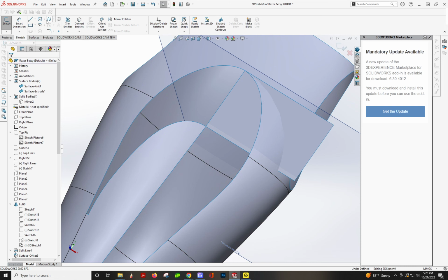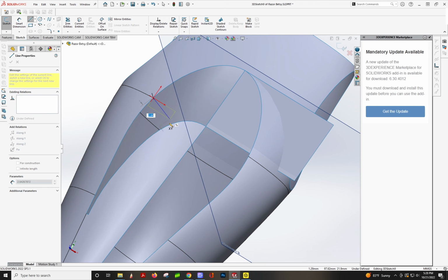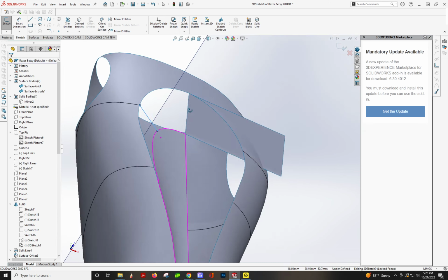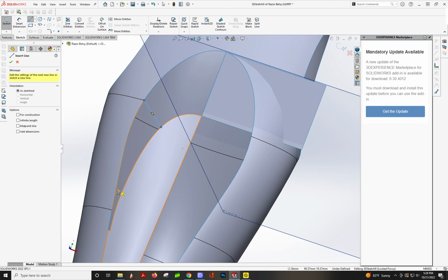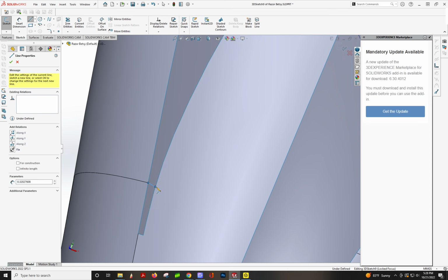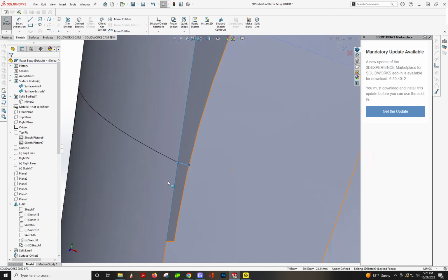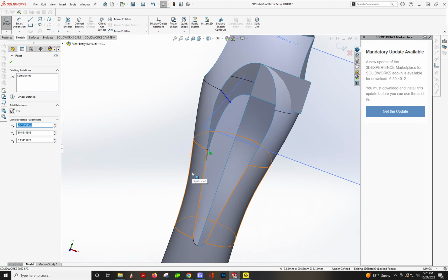And then we're going to do 3D sketch. We'll do one here because SolidWorks doesn't like these little edges. I'm going to have it line up with that arc and how it twists around. Maybe I don't need it, but this transition right here where there's this edge, I'm going to add one in. Clean this up a little bit here because it'll torque around otherwise.